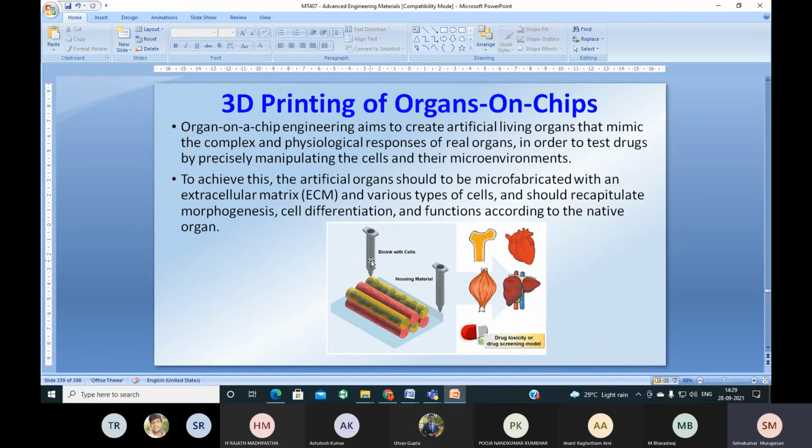So a nozzle like this will be there. You put your material in the form of hydrogel or some sort of solid form, and then you can melt it. With the help of a robotic dispensing system, this head can be movable in 3 directions, X, Y, Z. And with the help of CAD design, you can design the substrate or the material, how you want to fabricate it. Then you can fabricate the product, whichever design you would like to have.